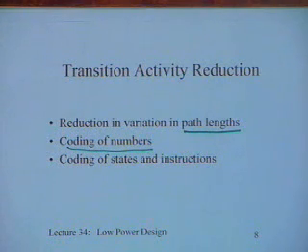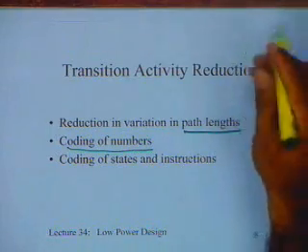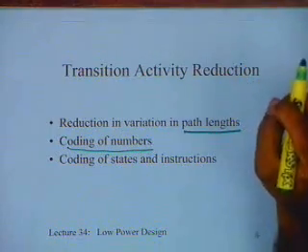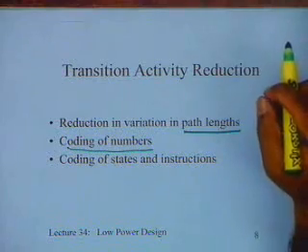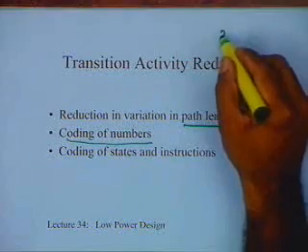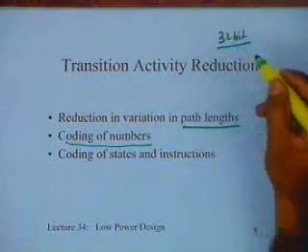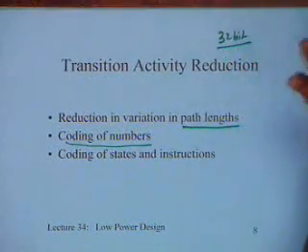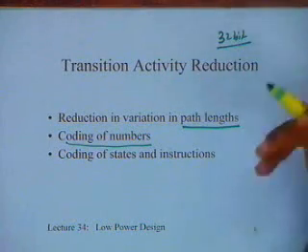It depends upon the nature of the data; you can work with the statistical properties of the data set that you are handling. For example, if you look at 2's complement arithmetic, and most of your computation happens in a very small range around 0, what's happening? Let's say you are using 32-bit arithmetic, but most of your numbers are in the range plus or minus 256 or 255.